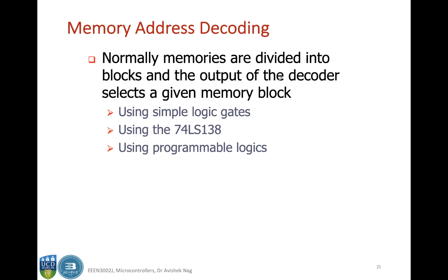The address pins are used to activate the several blocks of the memory, and those address pins go through an intermediate decoding circuitry, which can be implemented using simple logic gates, or using ICs like the 74LS138, or using programmable logics.